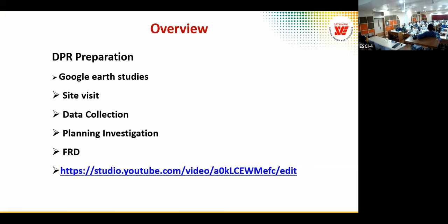Next step is the soil condition. In some projects you must have seen the contractor withholds the work for a decision on the category of the rock, whether it is soft rock, weathered rock, or hard rock. So there will be investigation, there will be studies, then after commencement of the work. Why was it not done in the initial DPR itself?